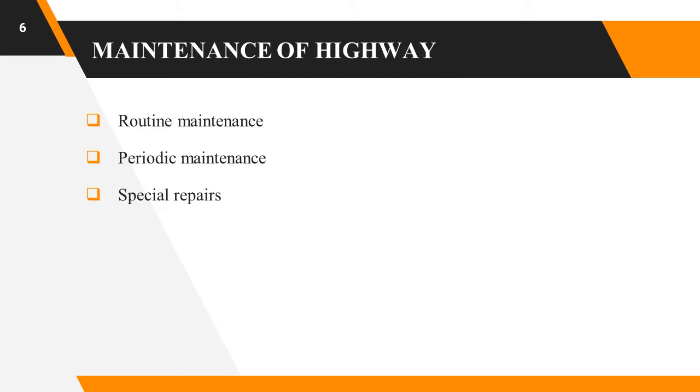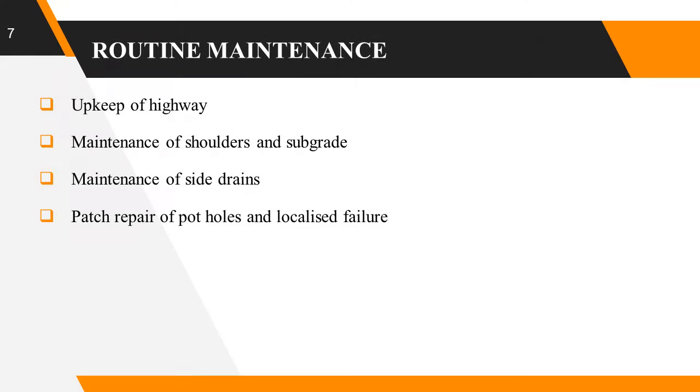And routine maintenance. Routine maintenance include upkeep of carriageway, maintenance of shoulder and subgrade, maintenance of side drain and other ancillary work, patch repair of potholes and localized failure.